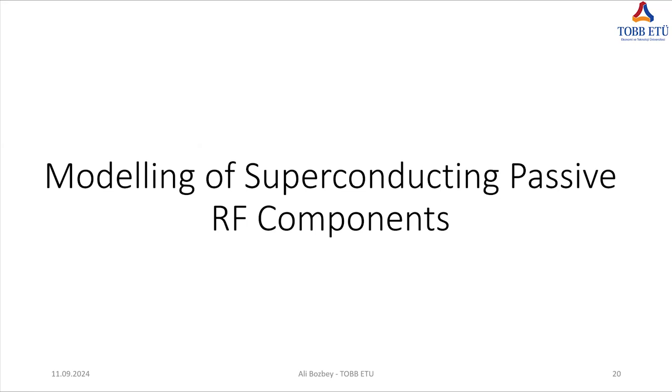In semiconductor circuits, inductors are usually ignored and considered parasitic elements, and the circuit elements are mainly based on capacitors, since it is a voltage-based circuit. In the case of superconductors, the circuits are based on currents, so inductors are the important element and capacitors are parasitic elements in general.